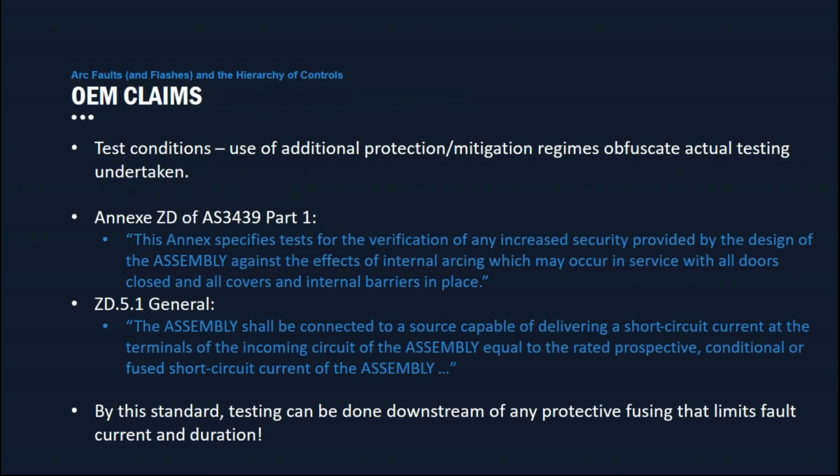OEM claims. I won't bore you by reading through all of the words here in the document, but in essence, the standards make provision for manufacturers to test their performance of electrical equipment in the case of arc faults and to publish those. And I do remember seeing a video of one stage where it was reportedly a 50 kA fault sustained for 2 seconds. And I watched the video and I could not believe what was in front of my eyes. And I was told that it was done in accordance with AS 3439. And I said, good-o, and went away and read it.